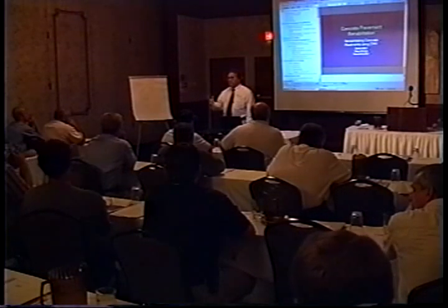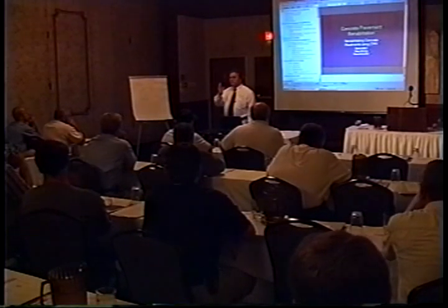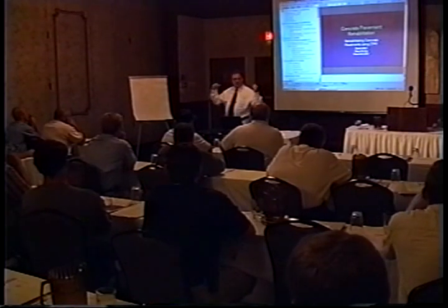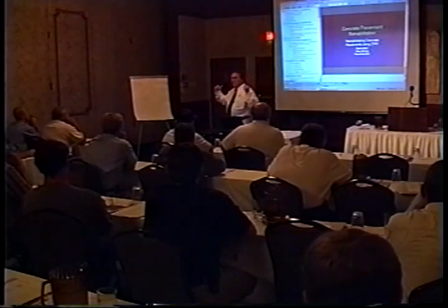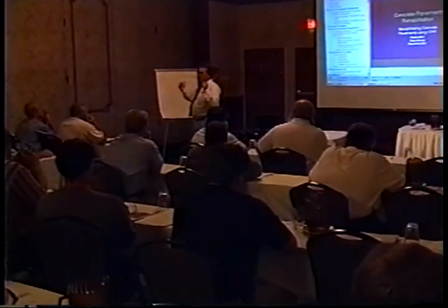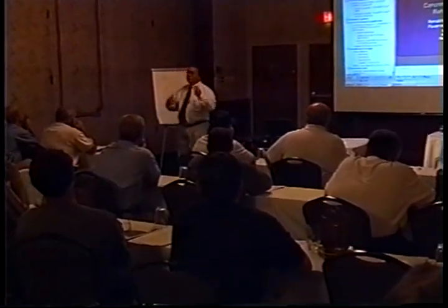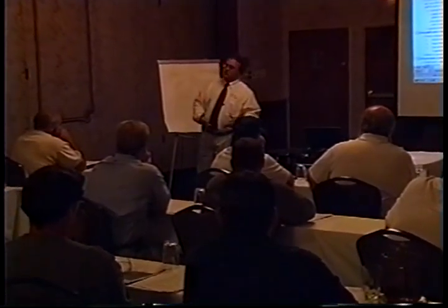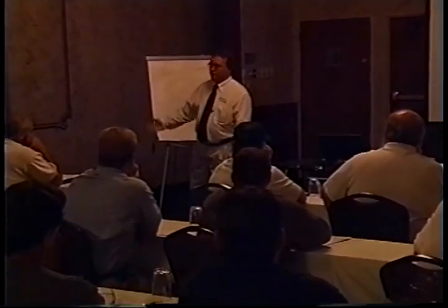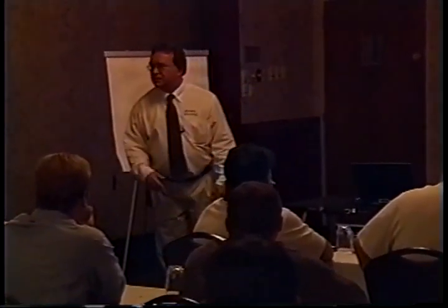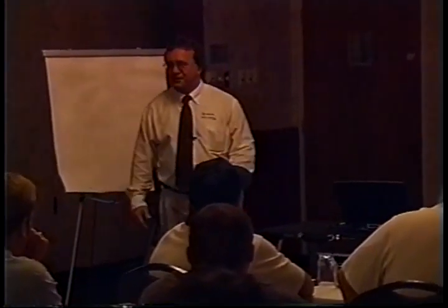The reason why I think we've experienced problems at the joints is because that's where the moisture collects. Now I'm going to let you guys into a little secret here. I've told you to keep your joints sealed. Well, there are some studies out there that say don't seal your joints. There have been studies up in Wisconsin that have said they see no difference between sealed joints in concrete pavement versus unsealed joints. They've done 30, 40 years of study on that. But they're about the only state who believes that. Nobody else believes them.